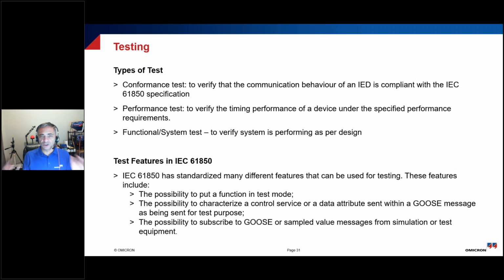The traditional way with the old electromechanical relays was to take the relays out of the system, test them to make sure that they were working properly, and put them back in. The problem was, when I was working for a very large electromechanical relay manufacturer, they reported back that more damage was done removing and installing these relays for the test than what would happen during their life.